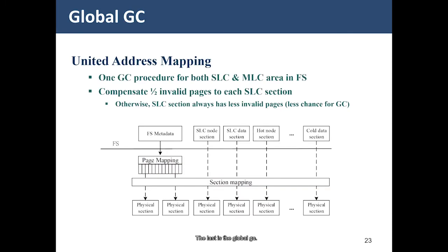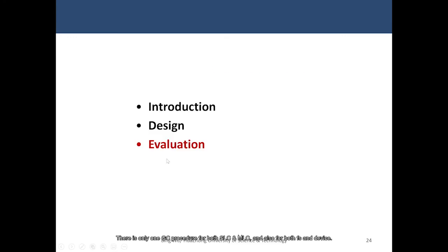Last is the global GC. We implement a unified segment mapping to align the FS management size and the device section size. There is only one GC procedure for both the SLC and MLC areas, and also for both the FS and the device.